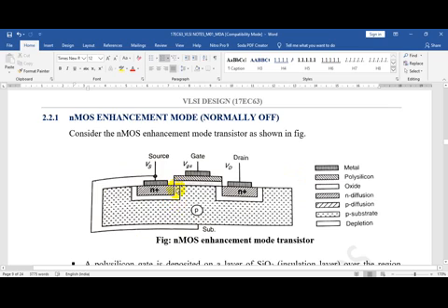That is what is shown here. Then you have a silicon dioxide layer. Upon that you have a polysilicon, and how are the connections taken out? By depositing a metal layer. You can see on this N plus type, you have a metal layer. From that the connection has been taken out, and it is the source.